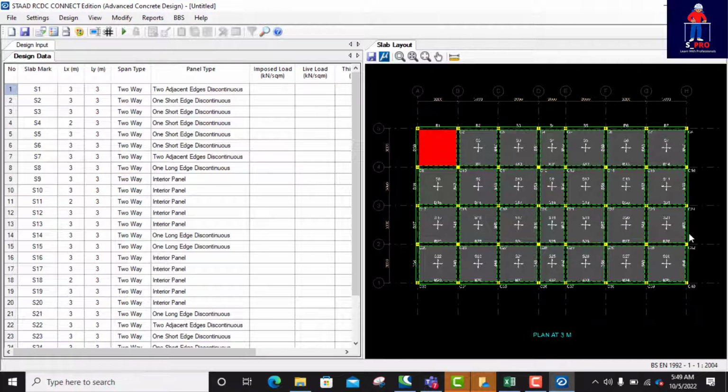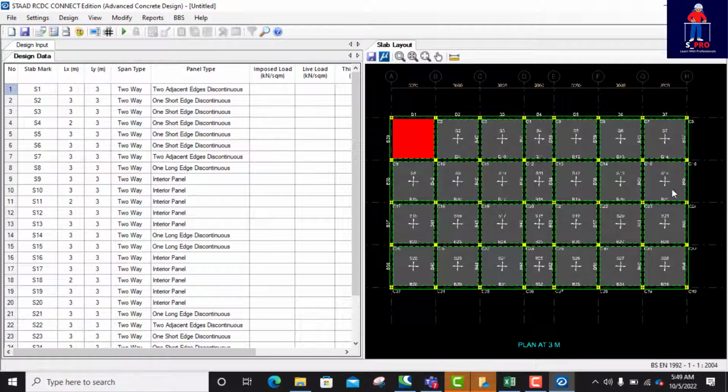That's very good. If you look at the preview here, you see all the panels. It has been paneled automatically. From here, you can generate your slab layout drawings. Just export to AutoCAD. In fact, in our next class, what we'll be doing is exporting of drawings to AutoCAD.